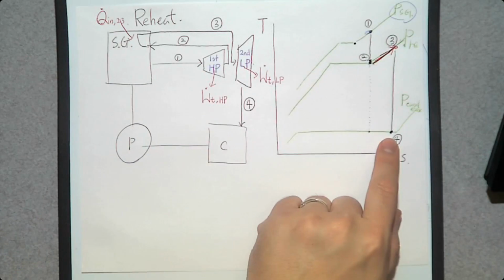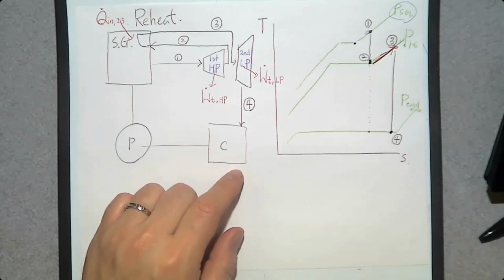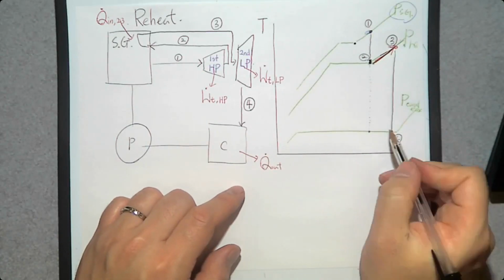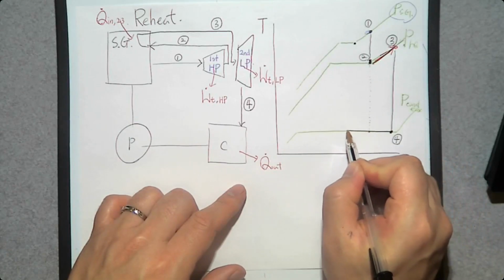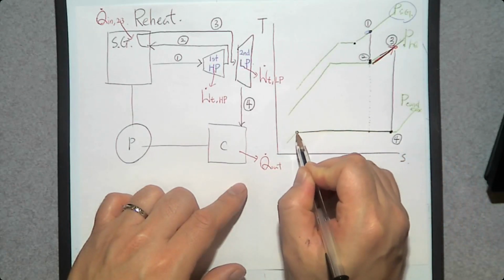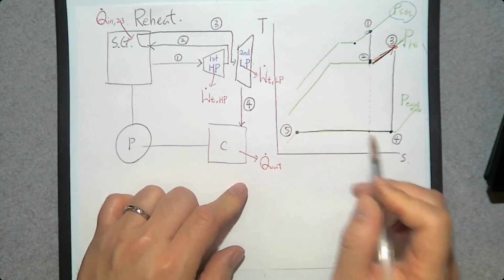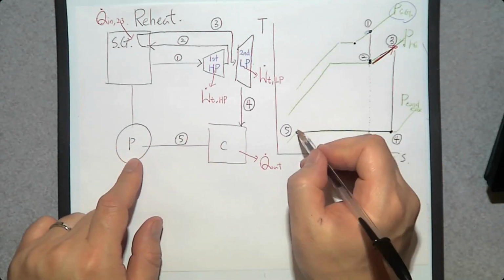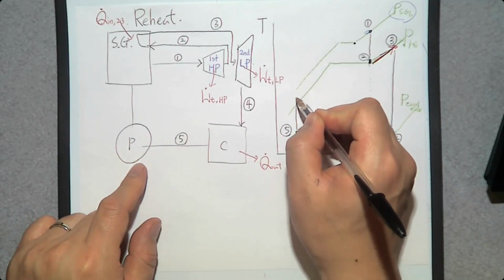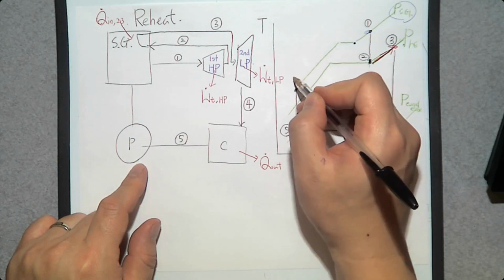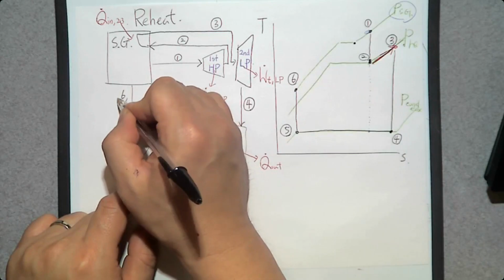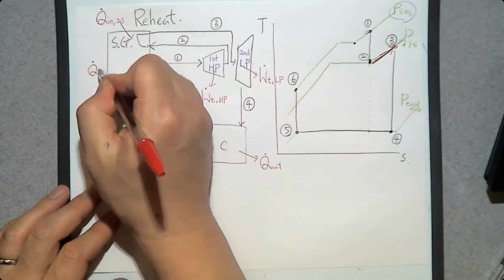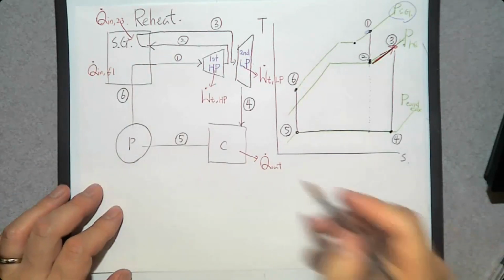And then once you enter the condenser, now we are rejecting heat, Q dot out, until all the vapor becomes liquid. Number 5, saturated liquid. And then it enters the pump, isentropically, temperature goes up, pressure goes up to number 6. And receiving heat between 6 and 1, Q in between 6 to 1 goes in.